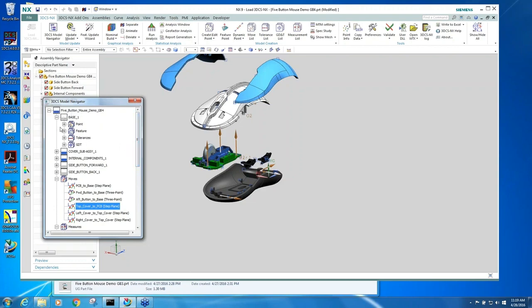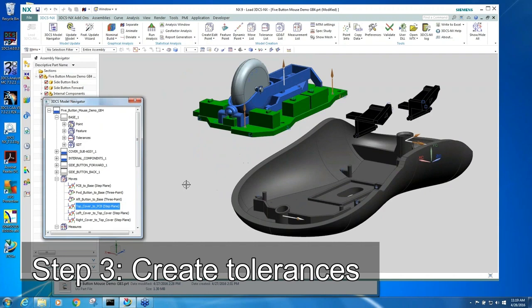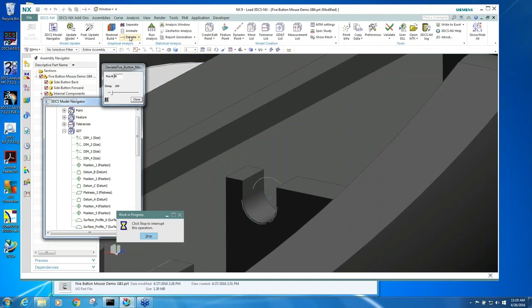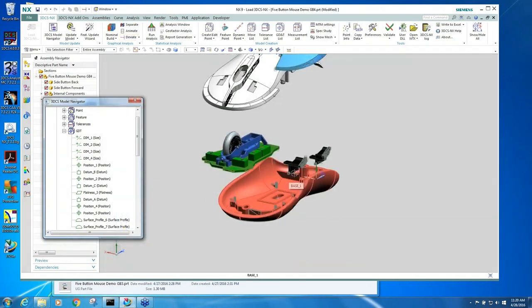And then at the part level, if I go into the base, the part level is where we actually have the tolerances. So now you can see that happens to be one of the features that locates the side mouse button. It's got a location tolerance on it. And so now when this number is changing because the model is not built, you're seeing component part variation. Every time this number changes, it's like we grabbed another component out of the box, it was molded, and this hole is within its defined positional tolerance. That happens to be the locator for the button.